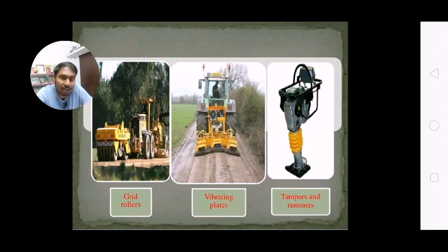Now vibrating plate rollers, that is vibratory rollers, also have immense use in the field to achieve the desired density. Vibratory compactors can compact granular soils to a very high maximum dry density. So this has an immense effect in the field. That is what we call a vibratory roller.